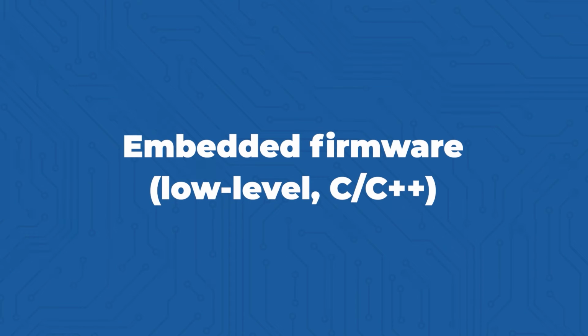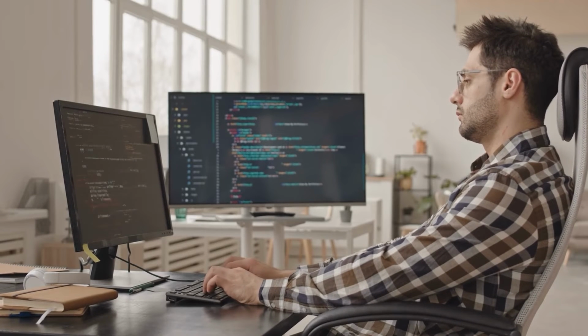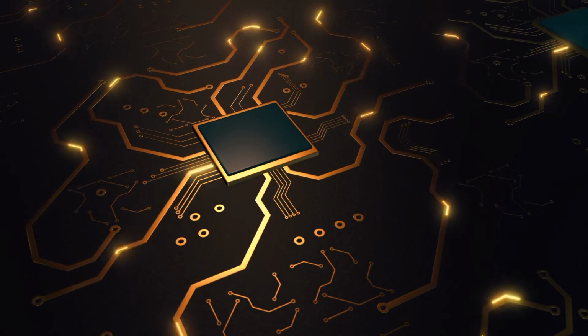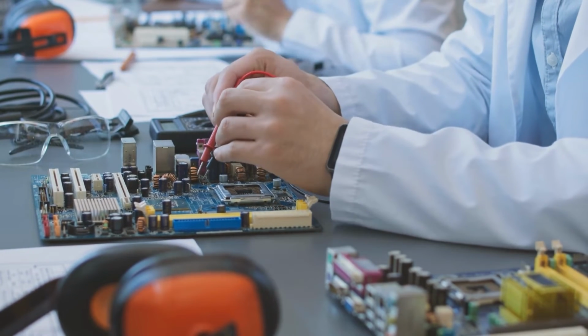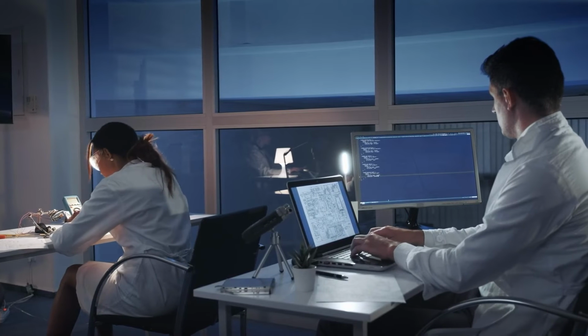That's the embedded firmware. And like I said, this typically operates much closer to the hardware. Whoever does this needs to have a solid understanding of the hardware. You don't have to wait to get your custom hardware design prototypes back before you can begin programming. You'll need your boards to finalize the program and to test everything out, obviously, but you can begin developing the firmware in advance or in parallel while you're developing your hardware through the use of development kits.